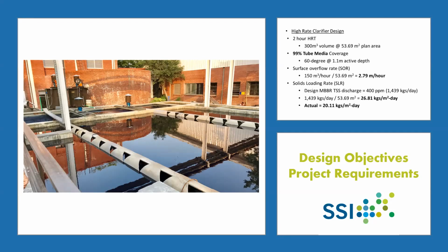So when we need to achieve high levels of BOD reduction, or I should say low levels of effluent BOD, the clarifier design does become very critical to the process. We want to make sure that we can remove that TSS, that is the biological solids, because it is carrying organics and nutrients. If you can't remove that, then you will continue to have high BOD or high nitrogen in the system.